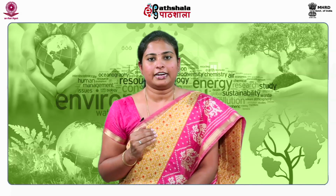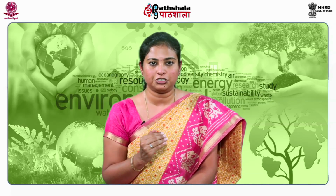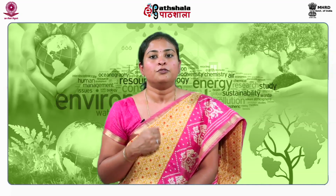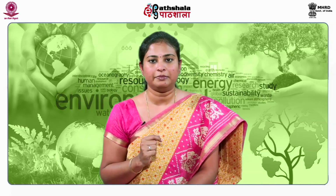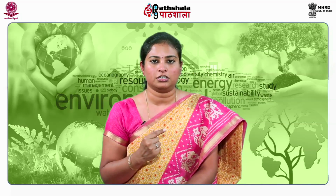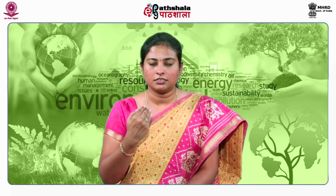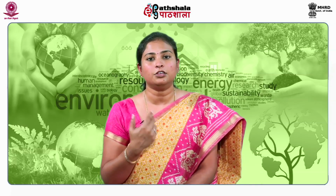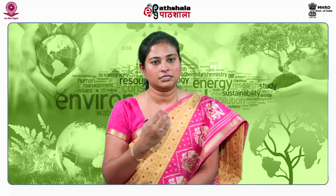So, a landfill bioreactor is an engineered landfill developed to speed up the process of waste degradation and promote environmental protection through a proper gas and leachate management system. Waste stabilization occurs within 5 to 10 years of implementation, but it requires a minimum of 35 to 40% moisture to increase the rate of waste degradation. At times when leachate is not sufficient to maintain the required moisture content within the landfill bioreactor, you can opt for other liquids like storm water runoff, wastewater treatment sludges, etc.